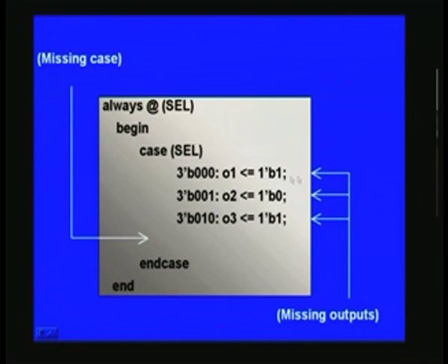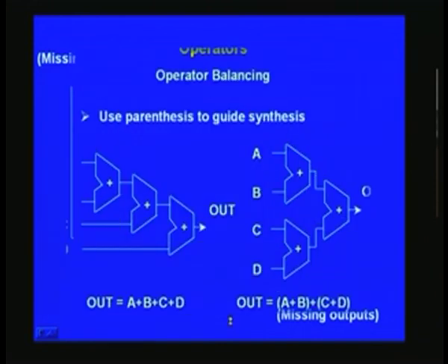So you should take care that you reset all the outputs. Either you can do it here, or you can have a statement earlier which will reset all the outputs right on the top. It may be better, although the code is a little lengthier, if you stick to doing it here, because while verifying your code, it will be easier for you. And that is what the example says.